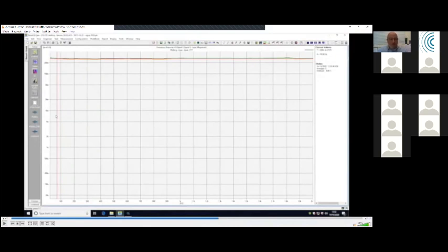Okay, so if we've done this procedure, we've now convinced ourselves that the acceleration and the force are being measured correctly, that the signals are being conditioned correctly, and that we've got confidence in the measurement system. So we use a simple mass, because when we go on to do more complicated structures, it may not be obvious what the response is going to be.